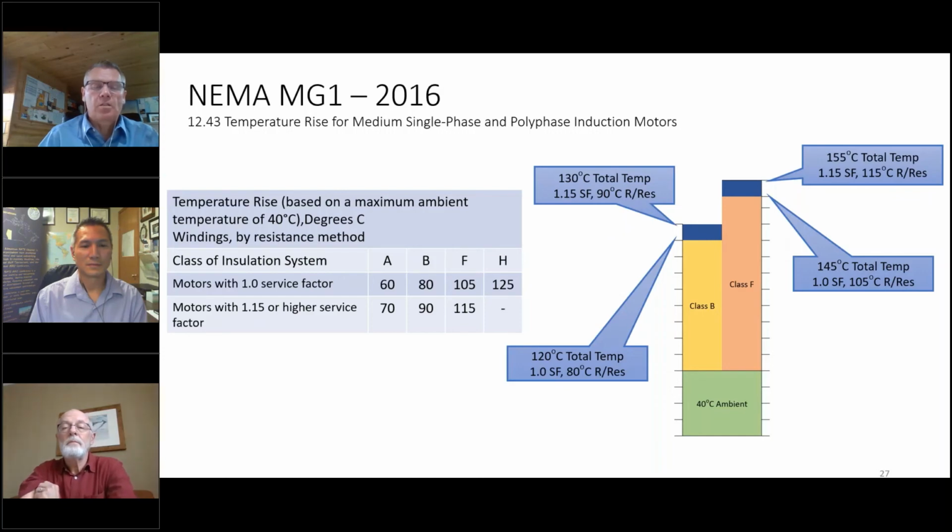So I think it's something like minus 20 or minus 29 is usually like the bottom end, and then you start looking at maybe some design changes for low temperature, or what sometimes we call Arctic duty. And a lot of it could be just a change of grease. Right. Okay. Thank you.